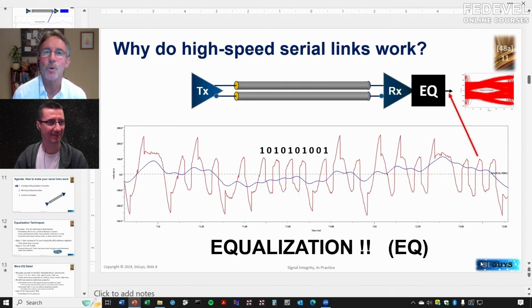And the importance is only increasing with data rate too, right? It's not becoming less important. It's becoming more important. Like I said, now Gen 6 is going to be like 5 times more equalization than Gen 5. Crazy, right? Whereas the PCB is almost doing the exact same thing because the fundamental frequency is going to be the same, right? But now it's going PAM4, so the equalization is now like 5 times more powerful.